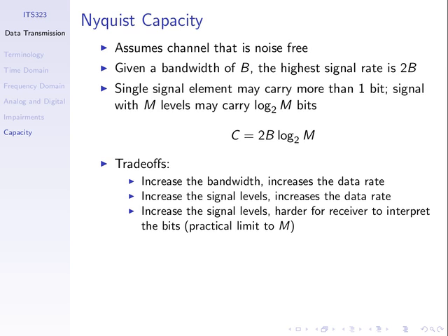If we measure -5.6, which level does it correspond to, -5 or +5? -5, easy. So if we measure it here, although it's not exactly -5, it's closer to this than this. Therefore, we'd assume the bits which were transmitted correspond to this level. And here, even though it's not exactly +5, it may be +4, it's still closer to this level.